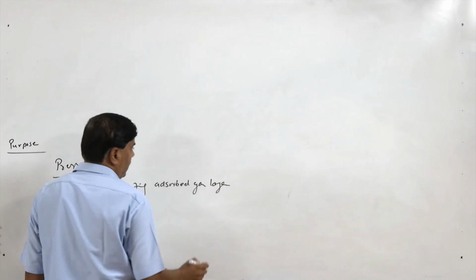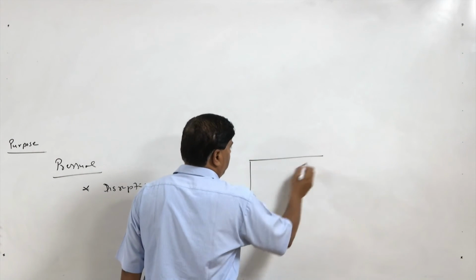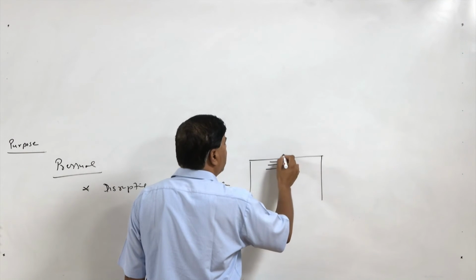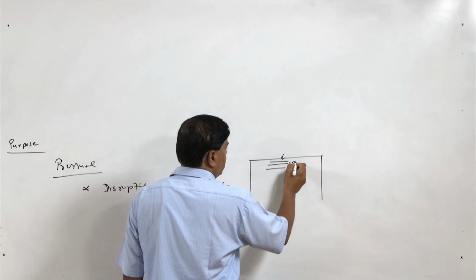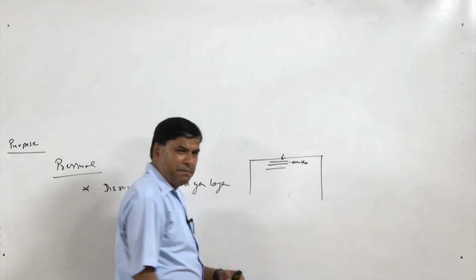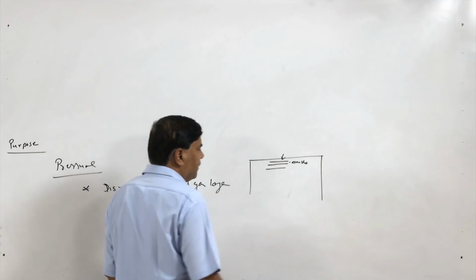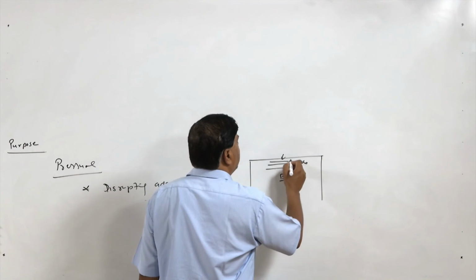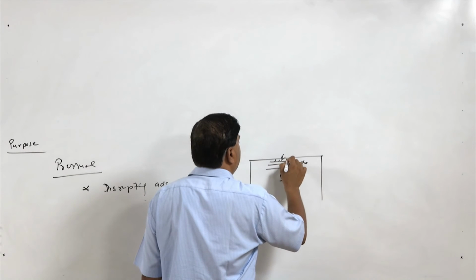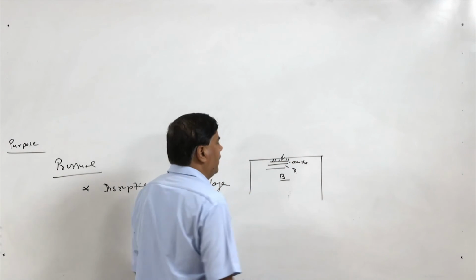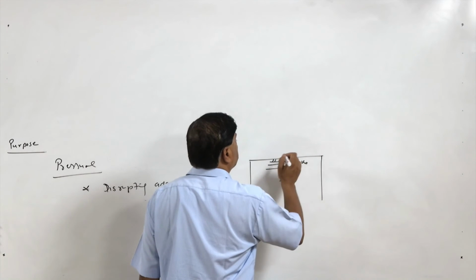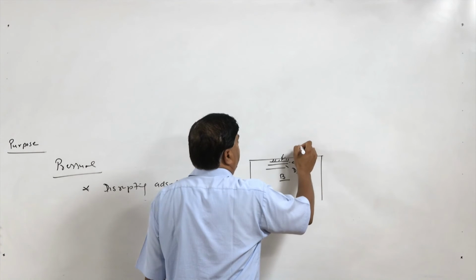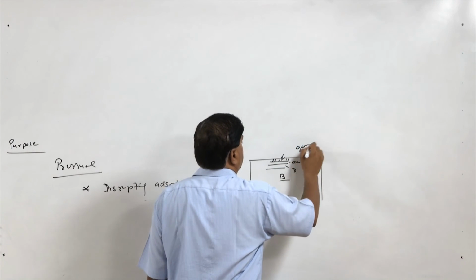We know that all the real components are made of a number of layers: this is bulk, this is the deformed layer, then the oxide layer, and then the adsorbed gas layer. The thickness of these layers may be at the nano level or the micron level. The surface at the very top, a few nanometers, has gases adsorbed from the atmosphere.